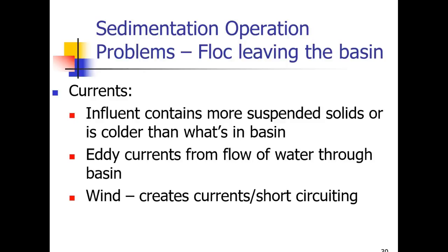The currents. The influent contains more suspended solids or is colder than what's in the basin. Eddy currents from flow of water through the basin. Wind can create currents and short circuiting also. And again, you always want to be all over this. And again, your weather can really play havoc with you.